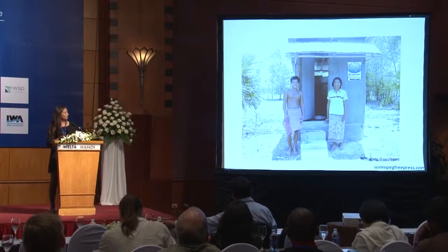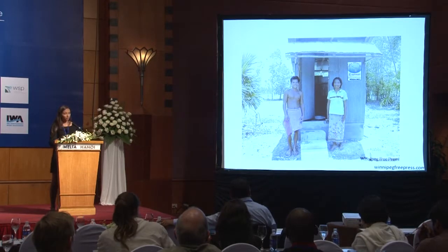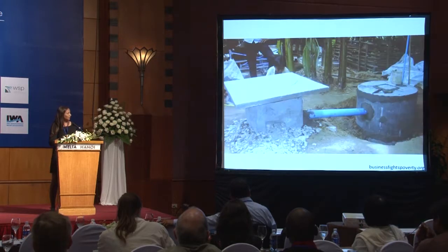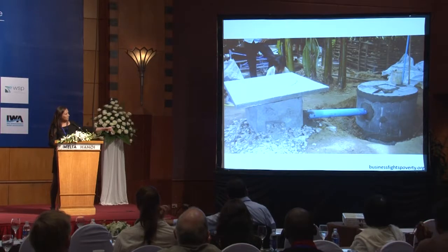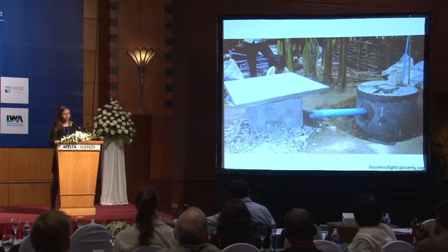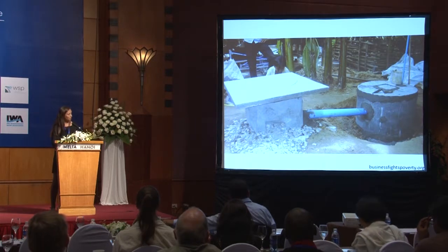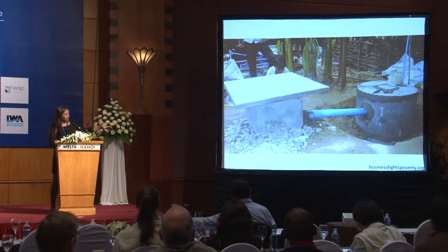So this is a typical latrine in Cambodia. It's a pour flush squat pan. This is what the inside looks like. So you have the squat pan that has a chamber box, a concrete box underneath, and it feeds into typically a 3-ring pit made out of concrete. And you can see it's sealed from the top, but it actually infiltrates from the bottom.